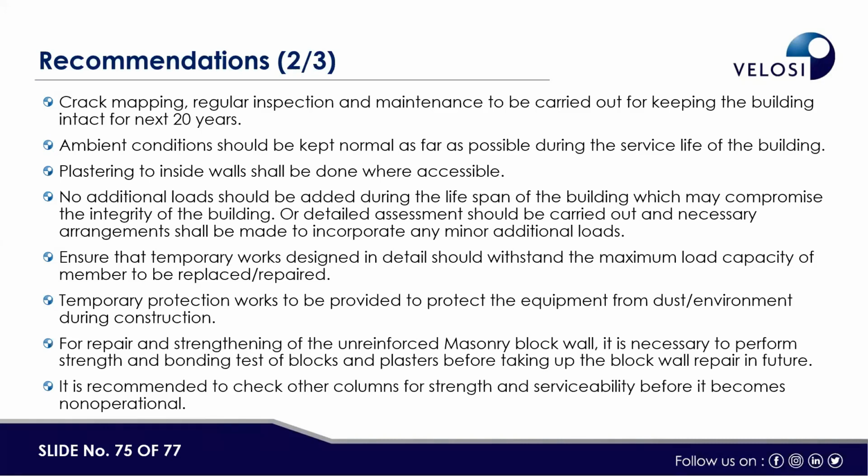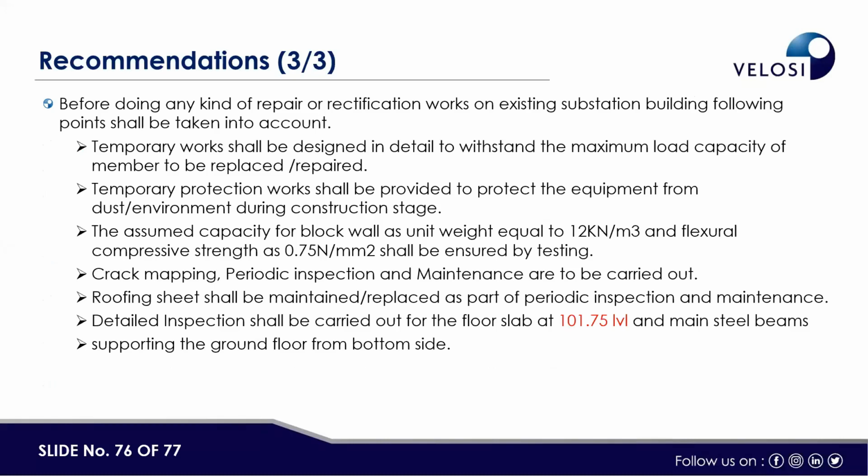done properly. For repair and strengthening of the unreinforced masonry block, it was necessary to perform the strength and bonding test of blocks and plasters before taking up a block wall repair. Recommended to check the columns for strength and serviceability before it becomes non-operational. These are the general recommendations.